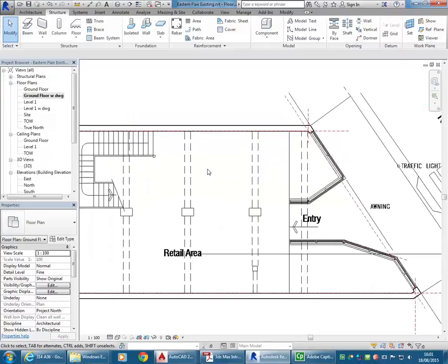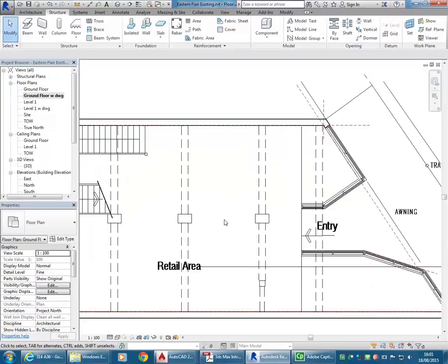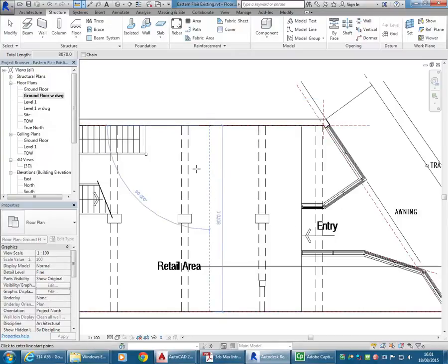Yeah. So just think about, if you're going to change the columns, remember that they're there for a reason. And if you take the columns away, you're going to have to rebuild the whole interior of the building. So you'd have to do a new roof and work out the span there, which is fairly decent. It's 8 metres, and work out the structure needed to span across that distance and support everything. And it's a big distance. You need a fairly serious floor structure and roof and ceiling structure as well if you're going to span that distance. So the other option would be to put new columns in as well to break up that span.